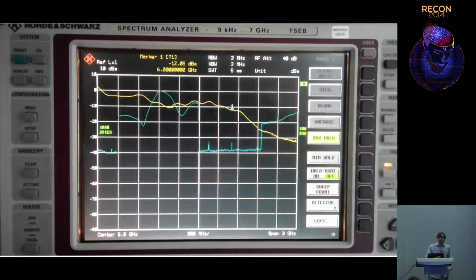Now, the fact that these blue curves aren't very flat, and especially the fact that we get that really extreme peak around 4.9 gigahertz, that's a result of the fact that I'm actually overdriving the front-end amplifier. I'm driving it into distortion, very similar to the way a guitar amp can be driven into distortion, which enhances the harmonics. Same exact thing happening, except we're in gigahertz instead of hertz.